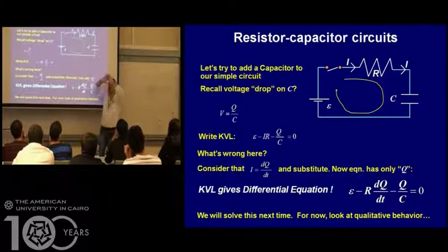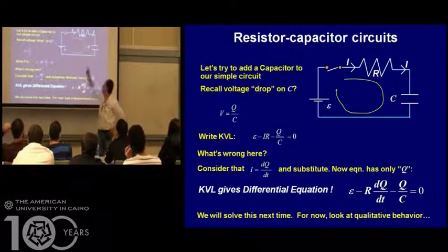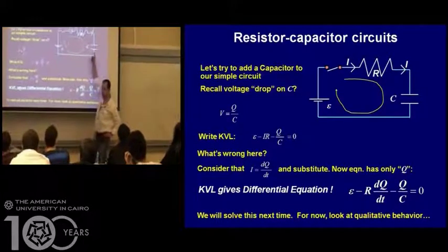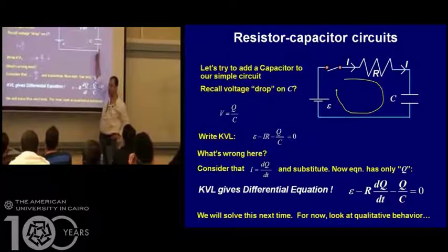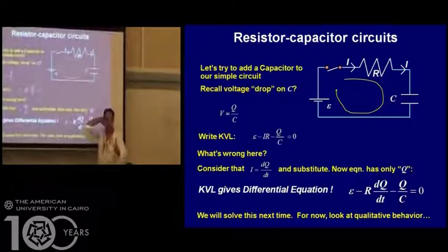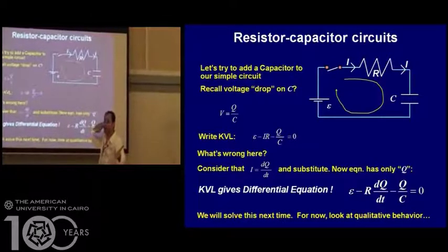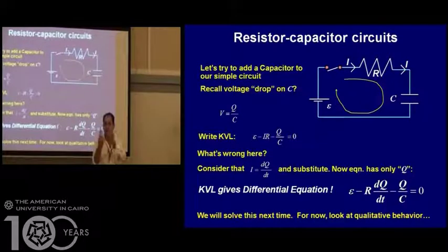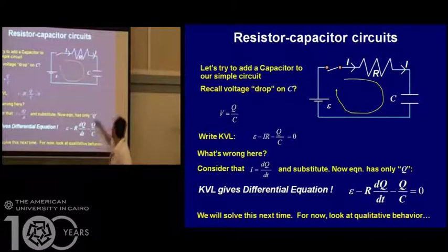Guys, you're answering something that I did not ask. I'm asking, once you switch the switch on, no charge will be on the capacitor. The voltage across the capacitor, across those two plates is going to be 0. There is no potential across them. This will act like something. And Kareem said it's going to act like a battery, and I told him no, it's not going to act like a battery because the battery has a potential between the two terminals. Thank you. This is going to be an equipotential surface.